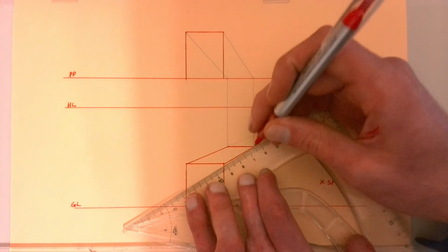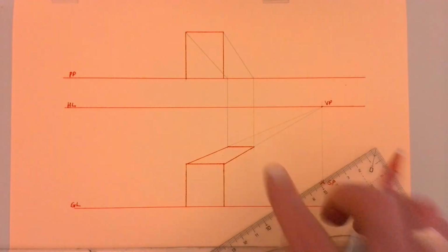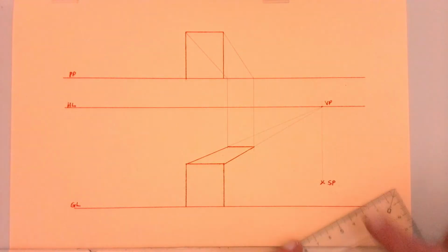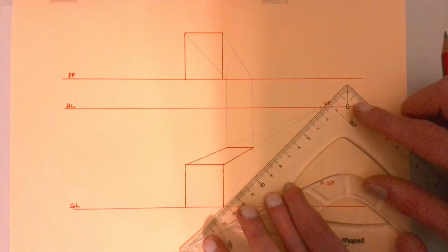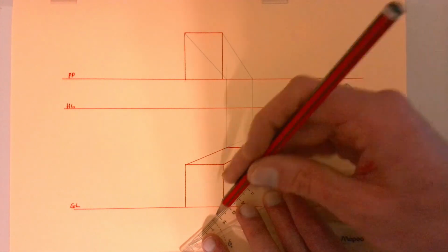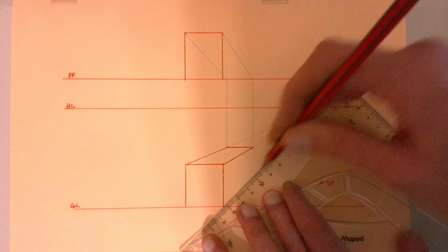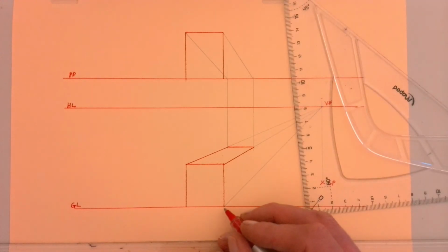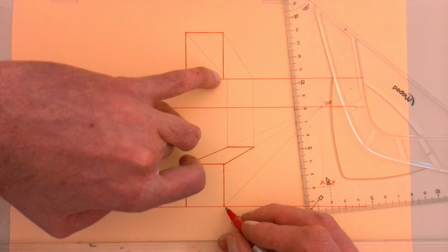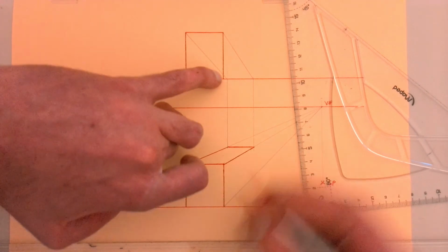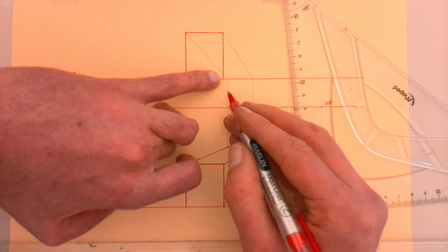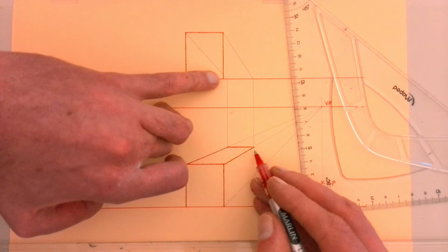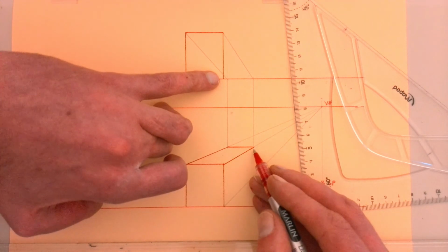Okay, we can see that clearly here. And now once we've got those lines, there's no need for us to project any more of our corners to our SP, because now we'll just take our other corners to our vanishing point, starting with this one. We take that in the direction of our vanishing point with a construction line, and then we know where that ends because that point over there also belongs to this corner in our top view, and that's because in our top view this corner actually represents 2 points, one at the top and one below it. That's the one at the top in the front view, and that's the one below it.